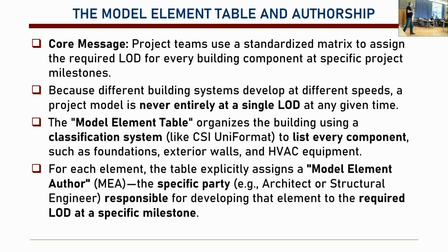Then we have model elements table. This is very important, and it's something that comes from the owner, okay? The project owner. What happens is that they basically create a standard matrix for different elements. You describe different LOD levels for different stages.